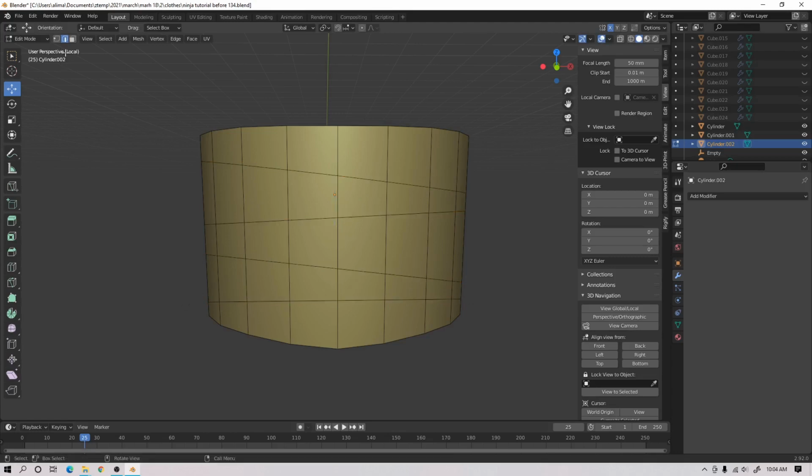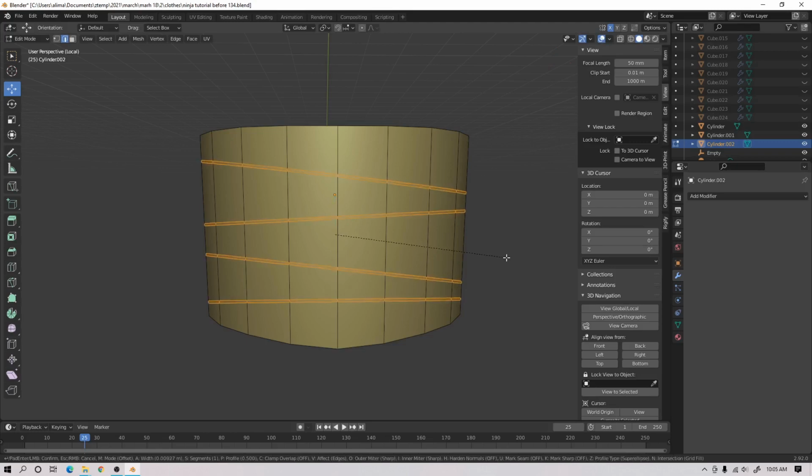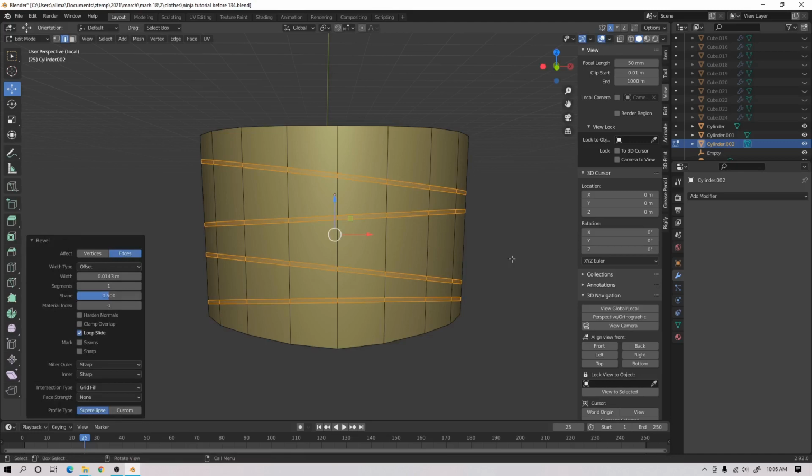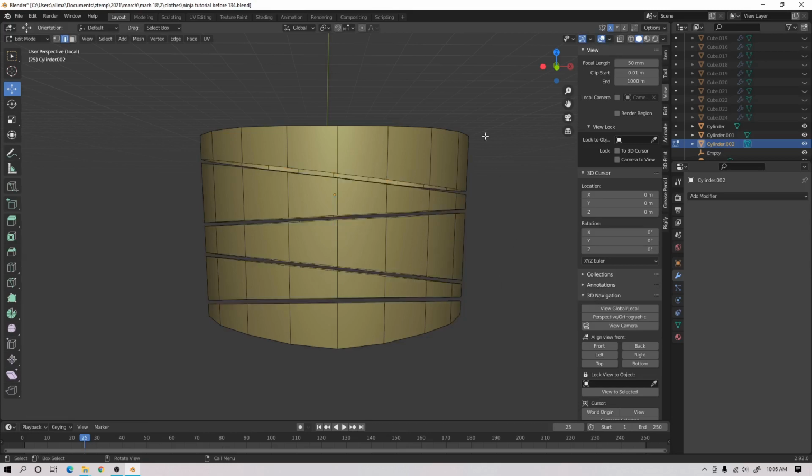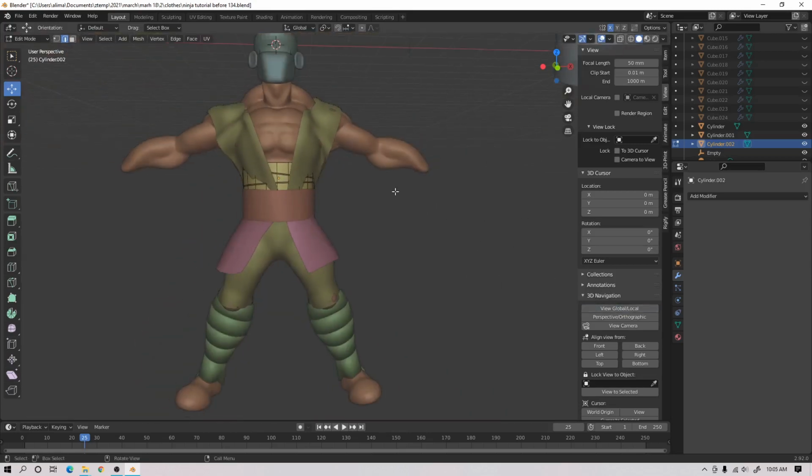So now with that done, with edge select, we'll hold Alt, select here, hold Shift while holding Alt, right? I'm going to hold Control, press B, holding Shift for fine selection. I'm dragging the mouse. I'm going to left click. I am going to press X and that brought up our delete menu, then choose faces to delete. Now I'm going to go to View, Local. I'm going to hold Alt here, move that up something like that.